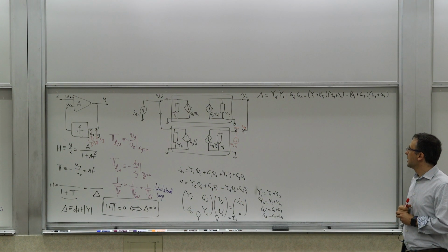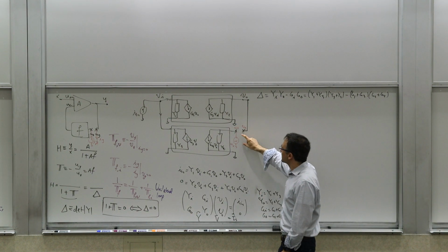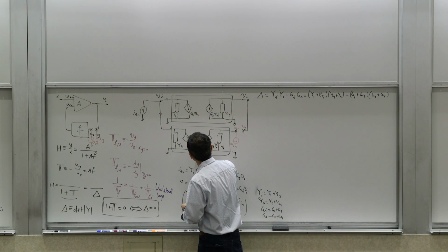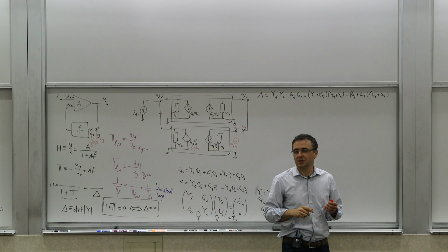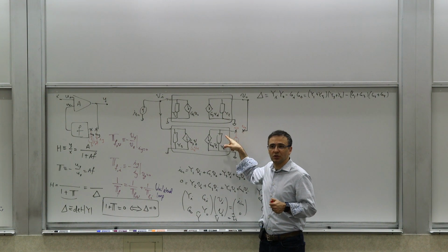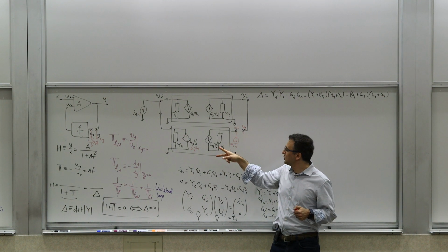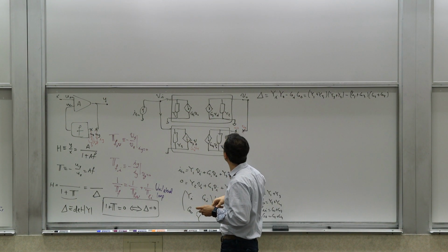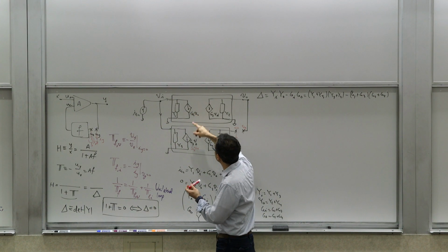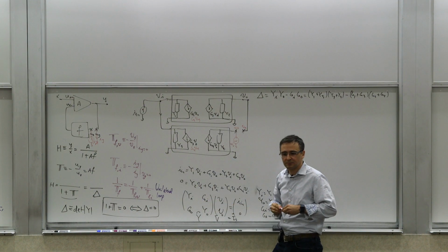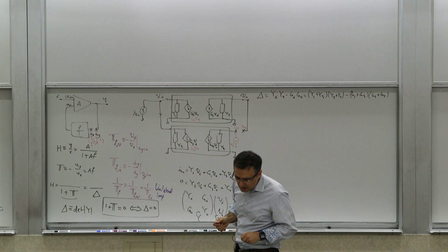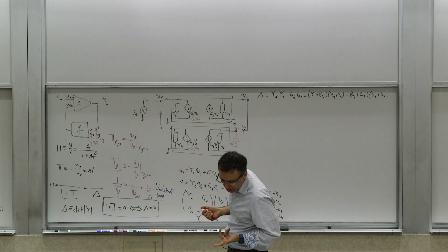So you can calculate this. It's pretty straightforward. If this is Vx, then this is going to be now Vo is going to, this is going to become Vx. This is going to become GmVx, right? Because it's the Gm times this voltage. Now it's Vx. So it's GmVx driving here, but that still remains Gm. So now this is G1 Vy. So if you take these 3, you can write 2 equations, right?